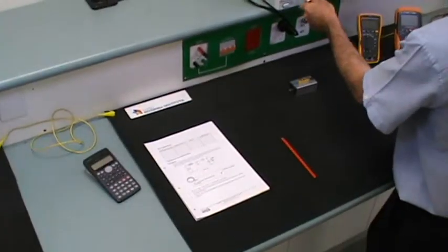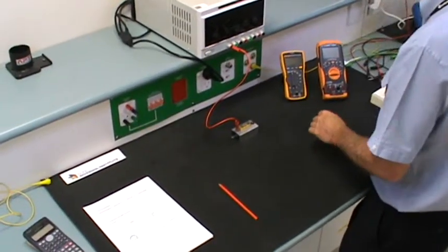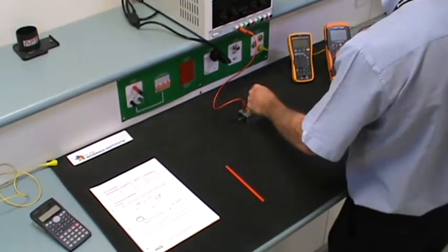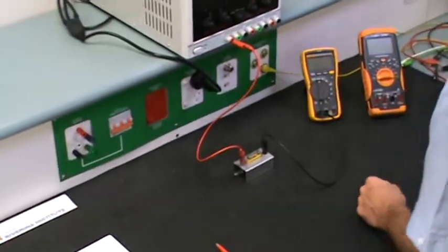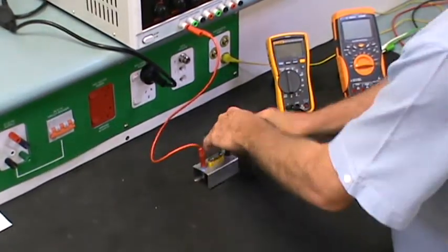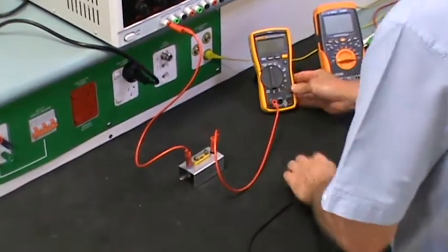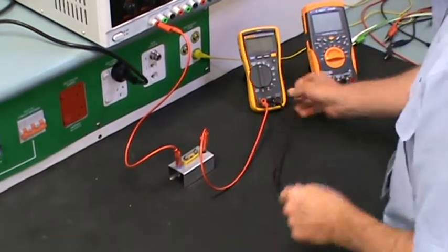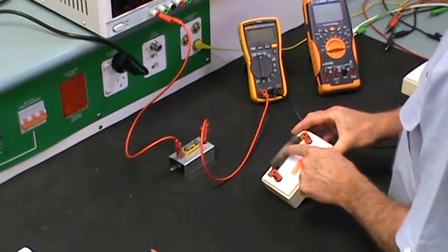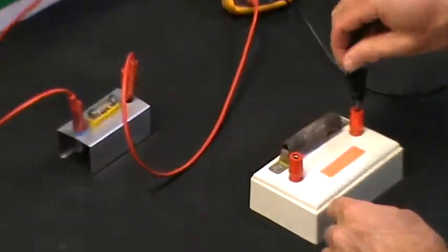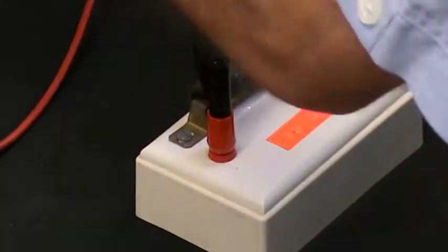So we've got the power supply into the fuse. From the fuse, I think we've been using black, yep, into the positive of the ammeter. From the ammeter, in fact we'll go red, so into the red of the ammeter. From the negative of the ammeter, into the resistor. In this particular case I've got a 10 ohm 25 watt resistor. So into there, and from the other side of the resistor back to home, or the negative of the power supply.